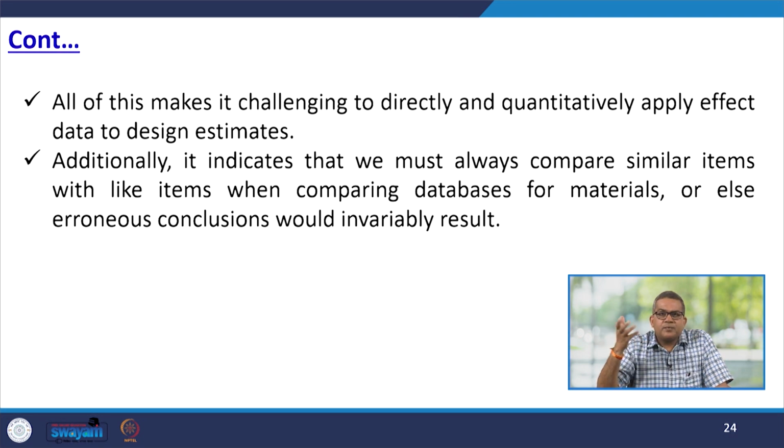Now, all of this makes it challenging to directly and quantitatively apply impact data to design estimates. Additionally, it indicates that we must always compare like items with like items when comparing data for materials, or else an erroneous conclusion would invariably result.